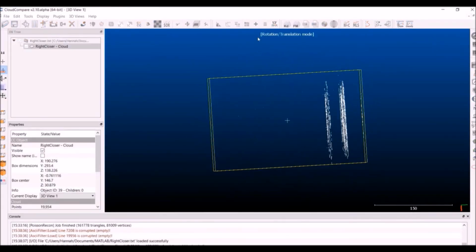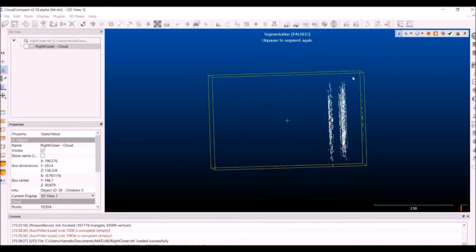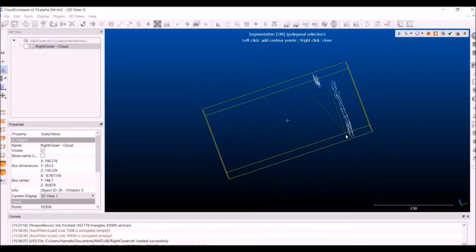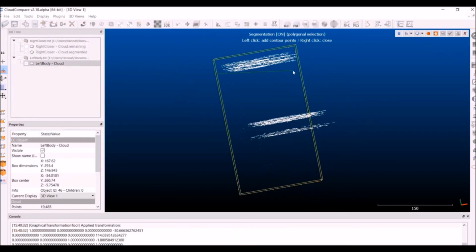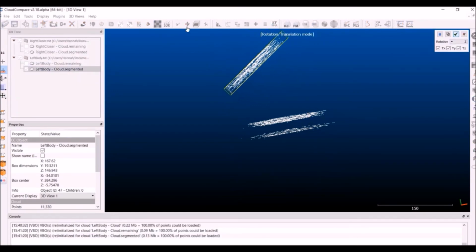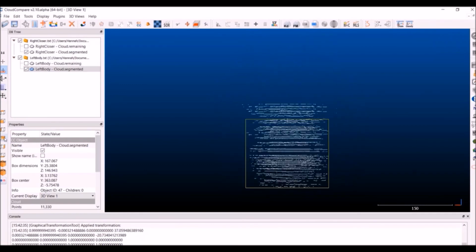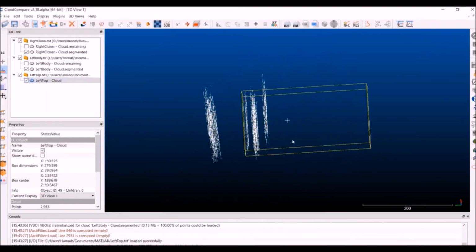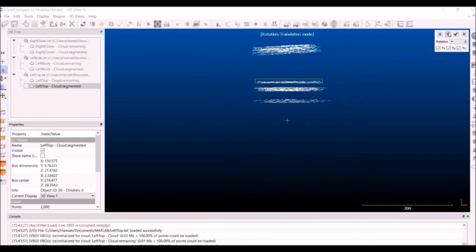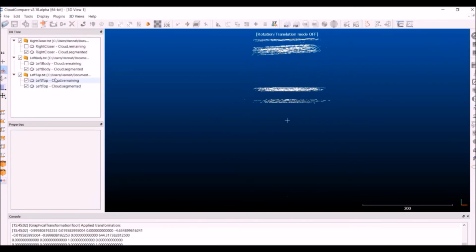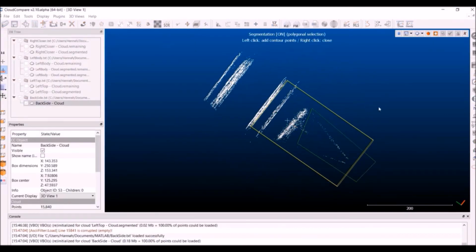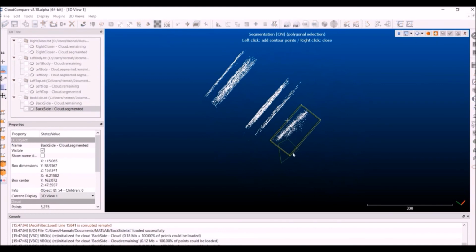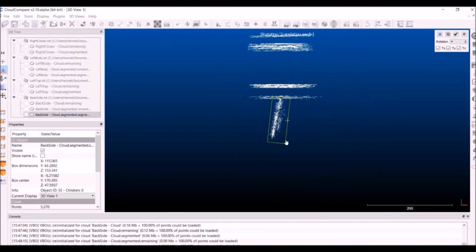Originally, I had done this filtering along with the rotation and stitching together of the three point clouds in Cloud Compare before generating my mesh. Cloud Compare has a lot of intuitive tools that allow you to do this filtering and stitching by hand, including a snip tool to remove points in areas where they don't belong, and a translation and rotation tool that allows you to orient multiple point clouds with one another. However, writing the MATLAB code to do this for you is a much cleaner and more automated method of achieving the same result. It also can take into account the location at which data was collected from in order to more accurately align individual point clouds.